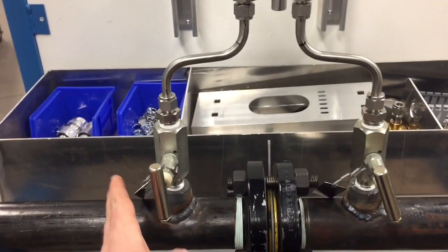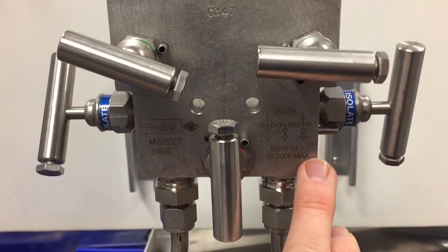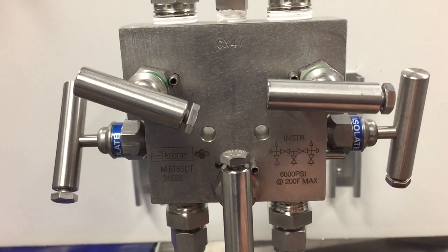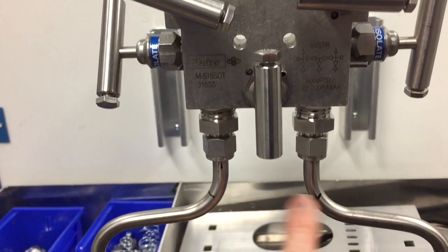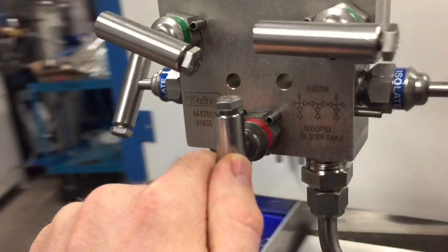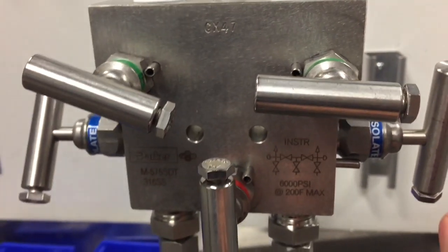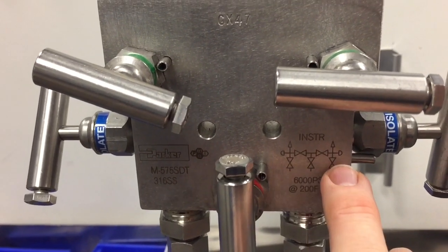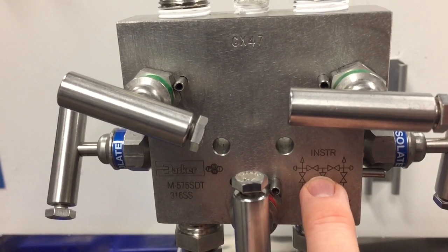As long as these 2 valves here are open, the 5-valve manifold, if you look on the diagram here, we've got a valve here and a valve here. Those are the 2 valves on the outside which have isolate on them. So if we were to close those, it would isolate these 2 lines right here. The valve in the middle probably has vent labeled on it. Yes, vent, and it is used for venting. So if we were to isolate here and here, shut these 2 valves, and open the vent here, it's going to bleed off any gas in the manifold.